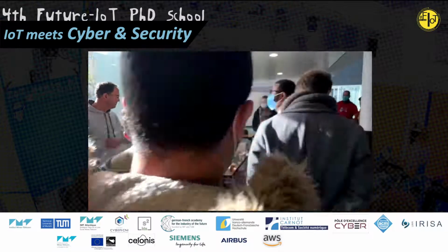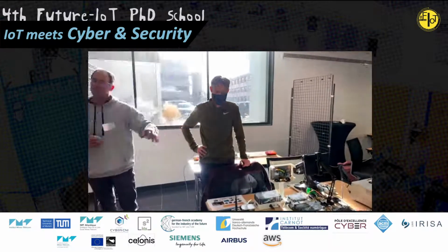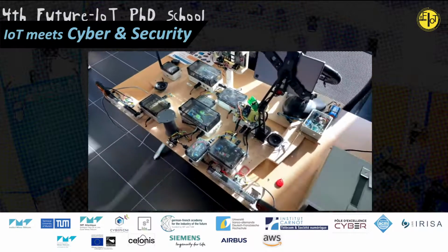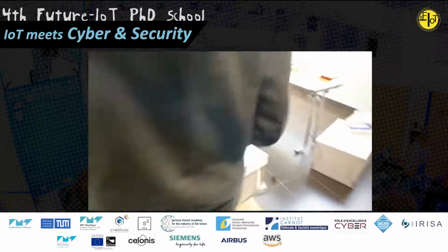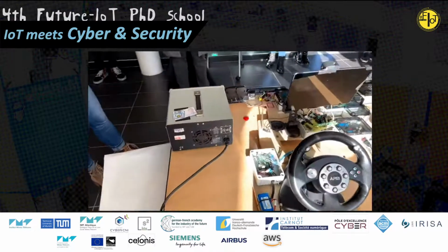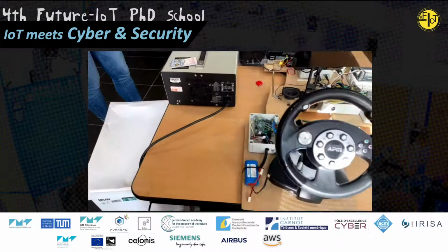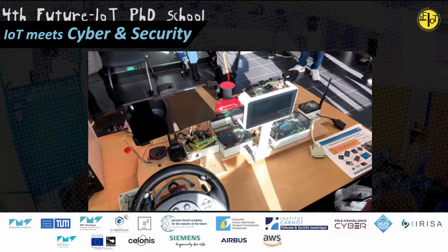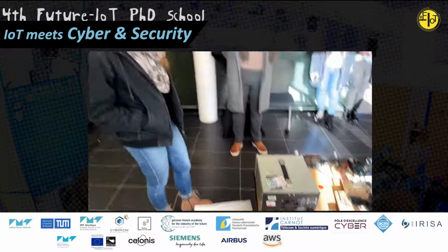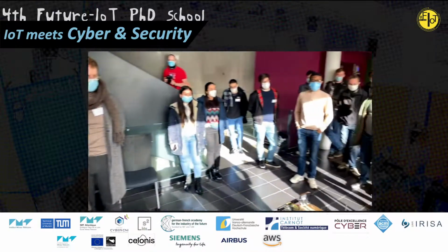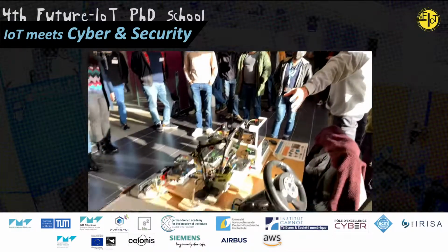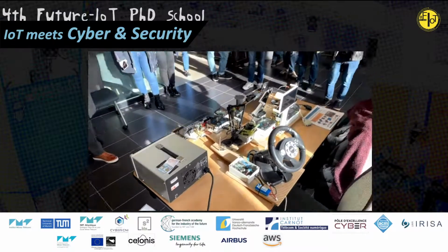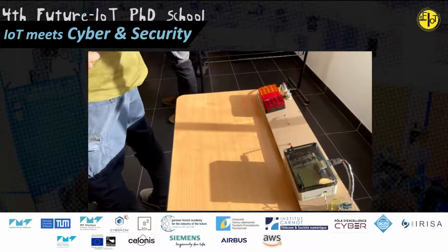So it's basically some professors at ISTIC have developed this system, which is a way of making a CAN bus like you have in a vehicle, using Arduino, Raspberry Pi, and different simple electronics that you know in your studies. So it's a way of allowing students to interface with the CAN bus and send and receive information as if it was in a real vehicle, but using open source solutions. All the electronics here is using CAN bus interfaces on Arduinos and Raspberry Pis. There's an infotainment screen with a Raspberry Pi, and you have several different internal buses communicating to enable the system to work.